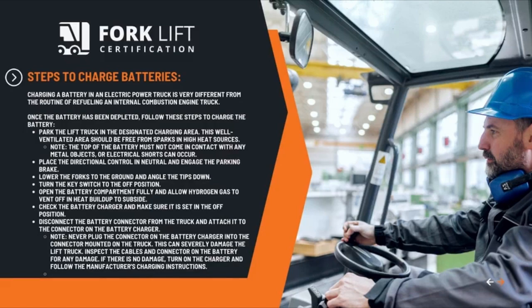Check the battery charger and make sure it is set in the off position. Disconnect the battery connector from the truck and attach it to the connector on the battery charger. Note, never plug the connector on the battery charger into the connector mounted on the truck. This can severely damage the lift truck. Inspect the cables and connector on the battery for any damage. If there is no damage, turn on the charger and follow the manufacturer's charging instructions.